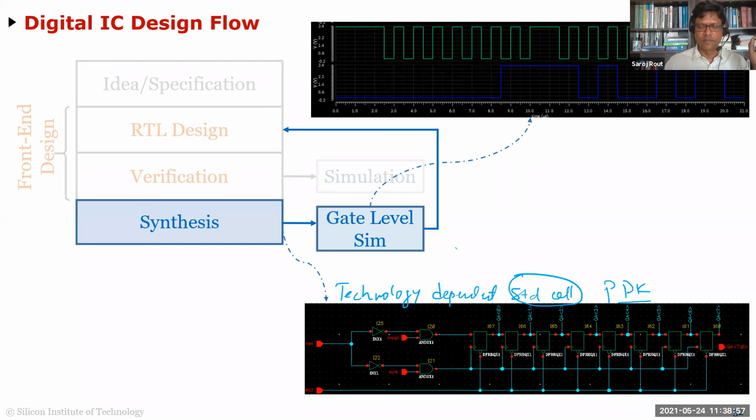It is computationally intensive, because once you get to the gate level, now you have to use the transistor level. Now, most simulators will not use spice level. That's just too slow. They will usually have what's called fast spice or table models and all that, which is kind of in between spice and behavioral models. For example, they will just take the MOS and model it as a switch. So your improvement in simulation time will be orders of magnitude once you do that. So that gate level simulation is done.